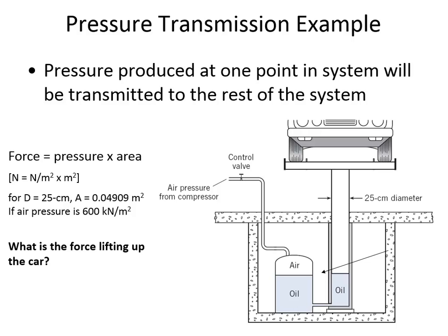The pressure increases a little bit as you go through the oil, because anytime you go down through the fluid, the pressure is increasing. And then as you go sideways, nothing happens, right? But then when you go up, the pressure is decreasing. Now these are about the same elevation. So the pressure here is going to be the same as the pressure acting up. So here's our pressure, and then the area that it's talking about is the bottom area of the cylinder.